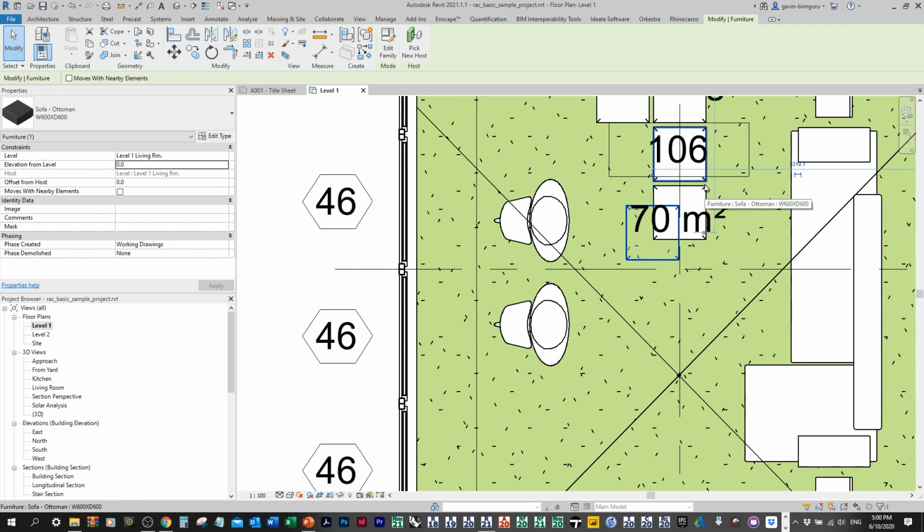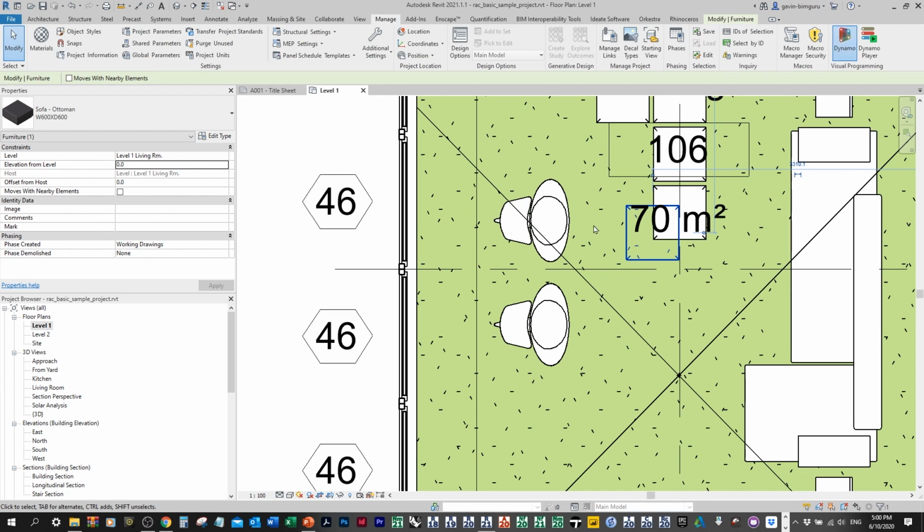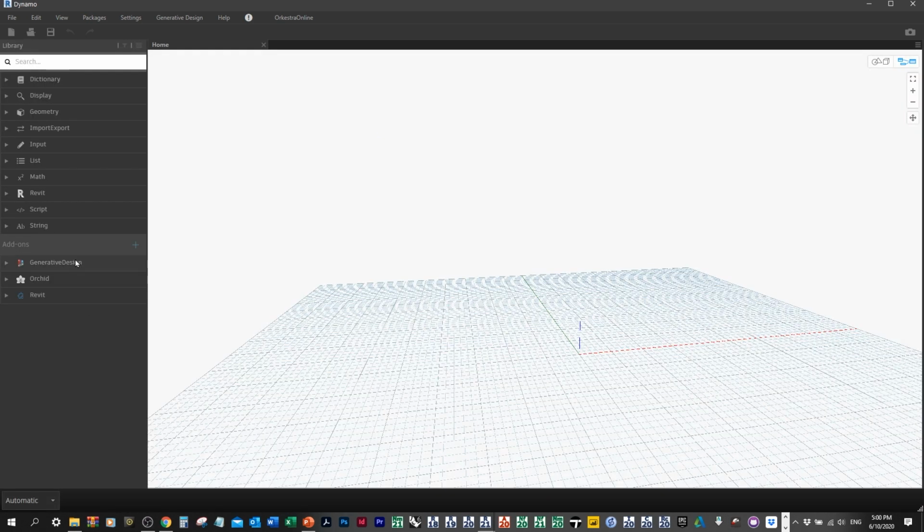In this case, the element creation probably isn't a very logical outcome, because I guess it's the point that we essentially tested from. But I guess this is where you could tell your script to send some points to at the end for that creation node. I believe you need a gate in Dynamo. I think that's the trigger for what stops it from creating until the very end. So in this case, or it might just not create elements by default, but I think there's a gate node. Yeah, so there's a gate node, and I believe that's what triggers the creation limitation.